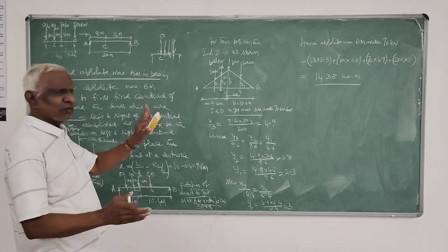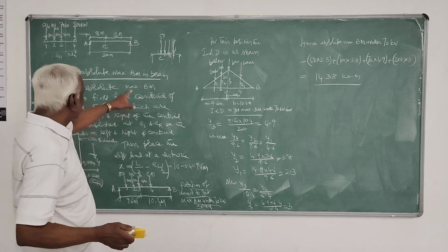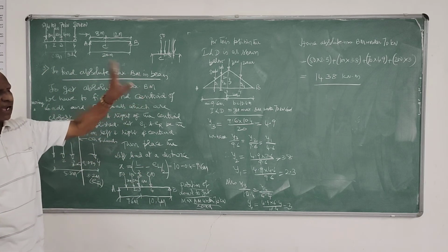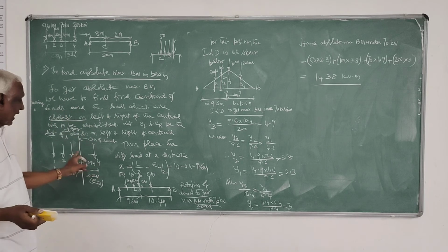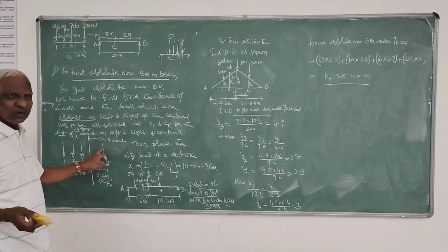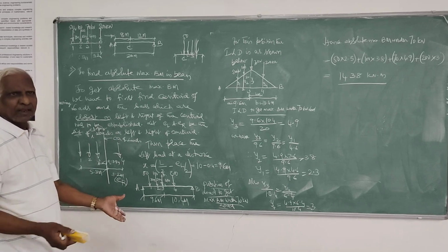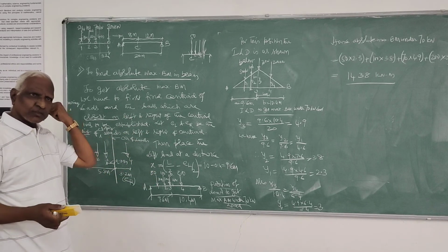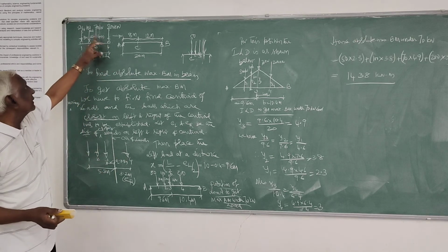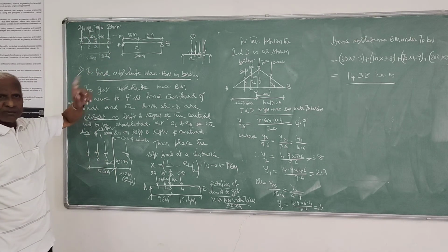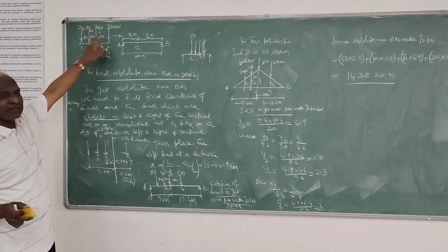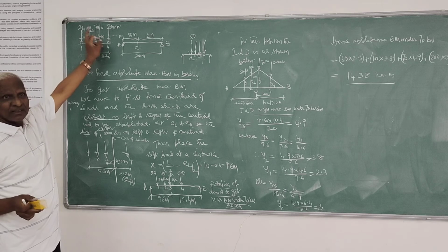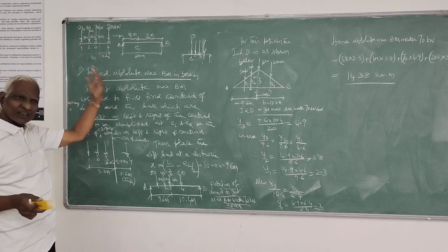So usually the load which is closer to the center, here this 70 kilonewton load is closer to the center, I have established. But I have a doubt with the other load, so you can also compute that and see whichever is more when you have a doubt. Otherwise, with one load, if they are of the same magnitude, you can just do with one calculation. But here I have a doubt now. This is about twice this. That is why it is better to work with that also.